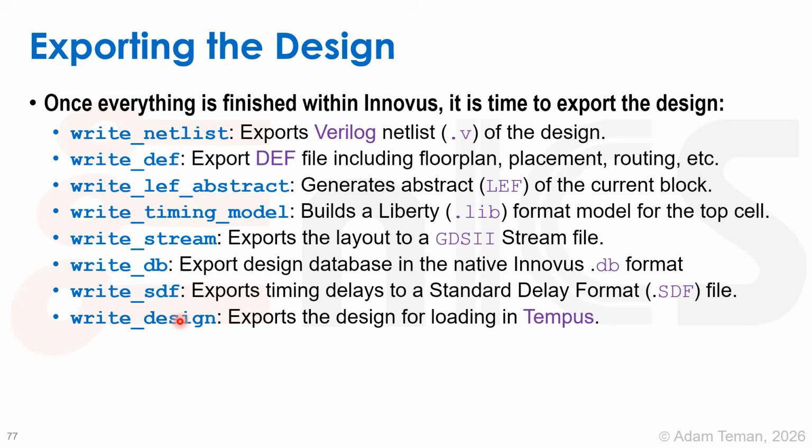And write design is a command which I am not sure why it still exists and if they are not going to replace it entirely with WriteDB. But export's designed for loading in Tempus. I assume that at least eventually, when we'll be able to load DBs into Tempus, this common UI is supposed to have all the tools load the same thing. But currently, at the current versions, write design exports a design for loading into Tempus in a bit of a different format.